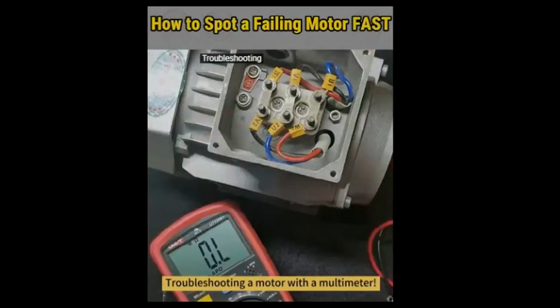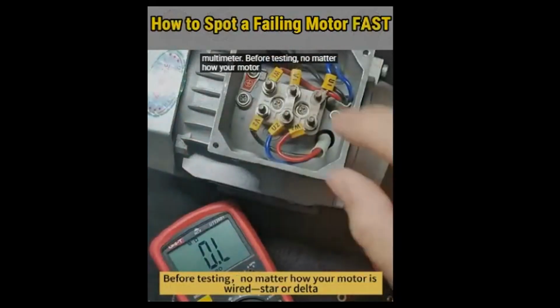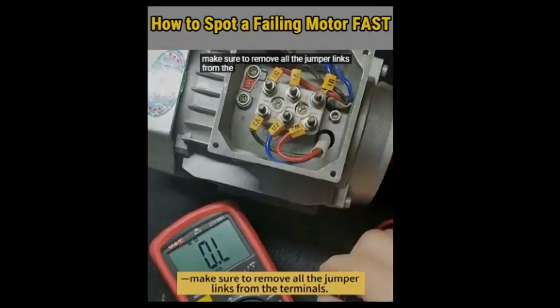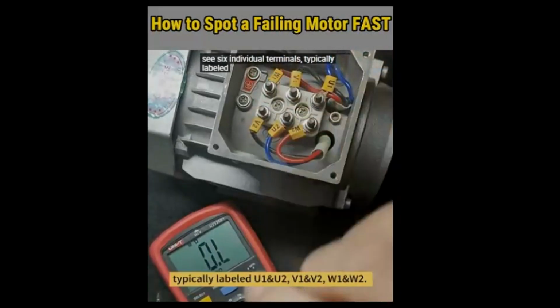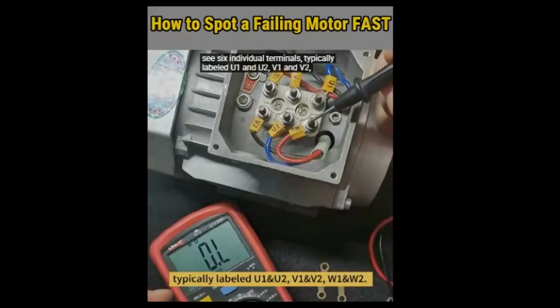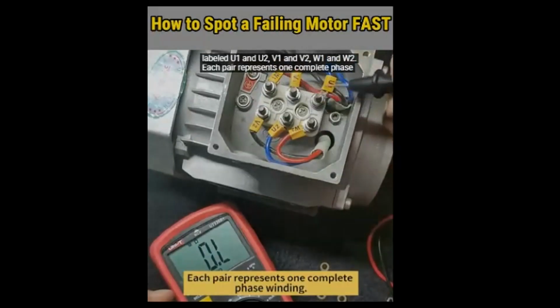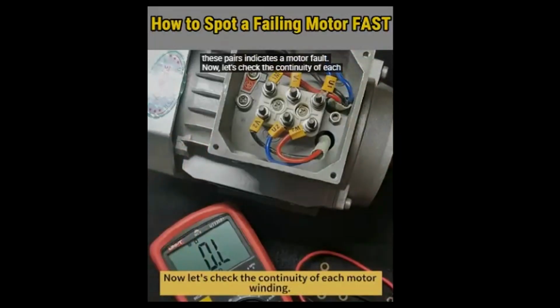A healthy motor: troubleshooting a motor with a multimeter. Before testing, no matter how your motor is wired, star or delta, make sure to remove all the jumper links from the terminals. Once removed, you'll see 6 individual terminals, typically labeled U1 and U2, V1 and V2, W1 and W2. Each pair represents one complete phase winding. Any break in continuity within these pairs indicates a motor fault. Now let's check the continuity of each motor winding.